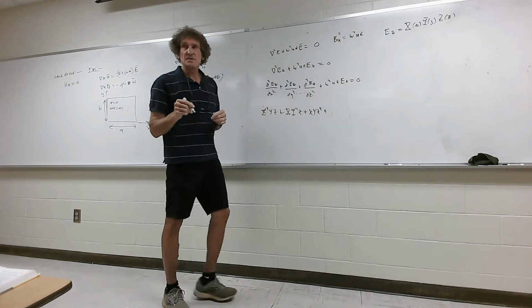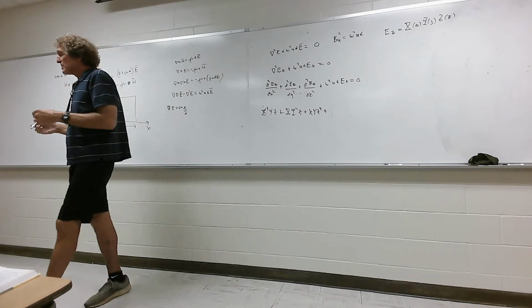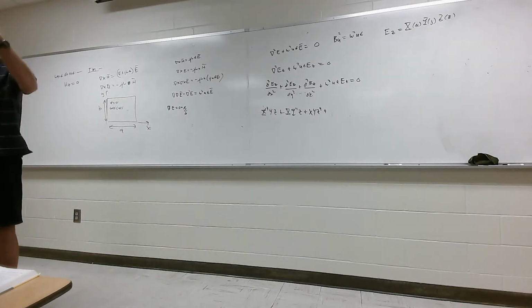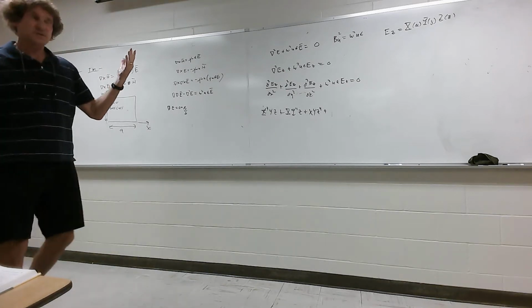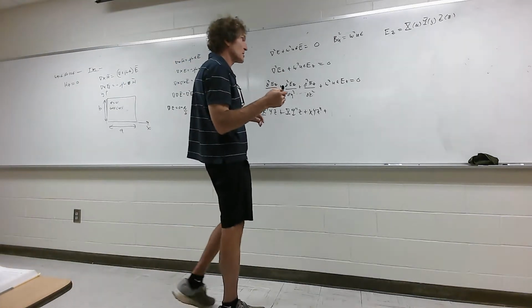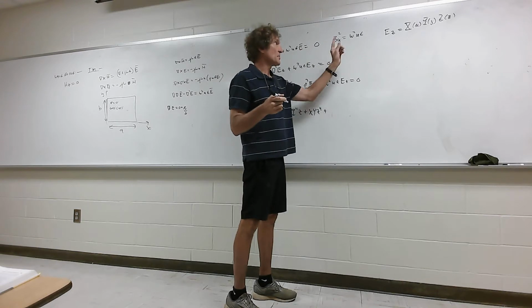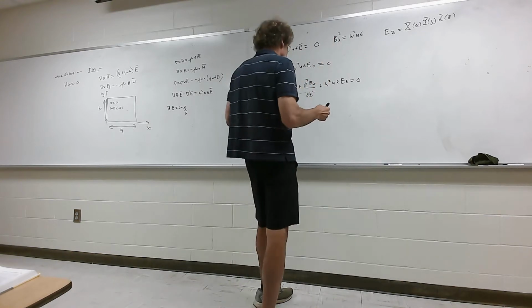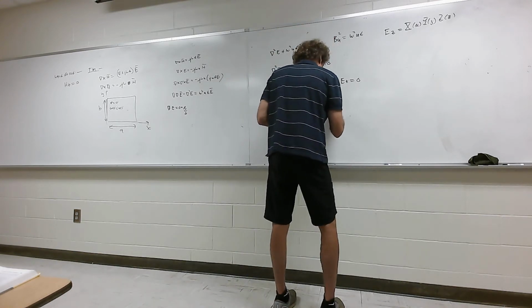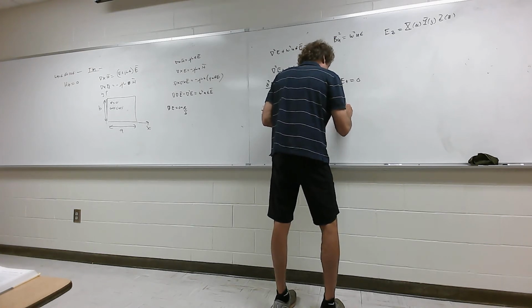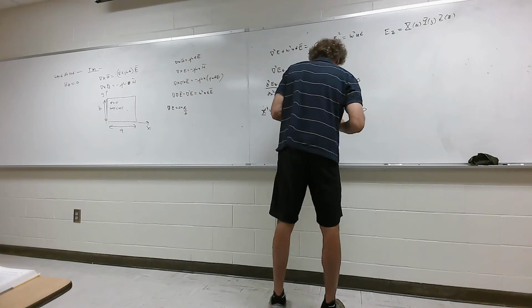That's consistent with his book. Beta is, of course, beta, and sub u means it's unguided. It's the same beta for free space. It's just equal to omega times square root of mu epsilon, or beta unguided squared would be omega squared mu epsilon. So I put that there, and then it's times x, y, z equals 0.